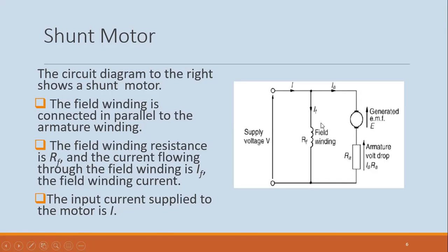All right. So remember, as current flows in this one too, you have flux being produced here in the armature. And how you get the rotation now is the interaction of the two fluxes, the field flux and the armature flux. And then you have rotation as we showed last week. As the machine rotates, it cuts the field flux, and you have an induced EMF.